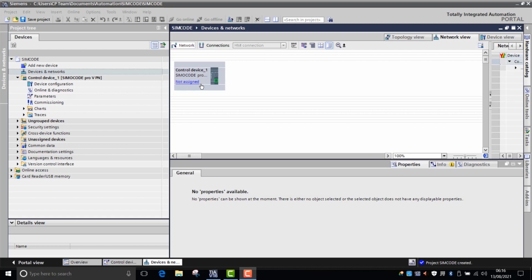A power monitoring solution can. For example, in an industrial facility, peak demand charges might be larger than the energy charge. So software that detects when the plant is at its peak demand and then maps each cost centre's contribution makes the allocation of energy costs more accurate. Now SIMOCODE doesn't do that, but it can monitor the power and feed it to a piece of software that actually does that.